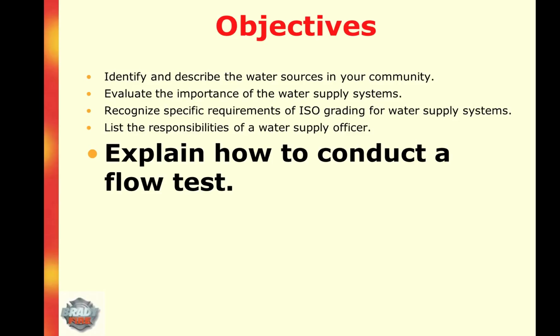A complete understanding of the water supply distribution system improves firefighting strategies and helps the fire department overcome any deficiencies that they identify in the water system. Fire inspectors should obtain water maps of the local utilities that identify the size and connections of the underground water mains. The flow test procedure is outlined in NFPA 291, Recommended Practice for Fire Flow Testing and Marking of Hydrants, and should be followed by the fire inspector.